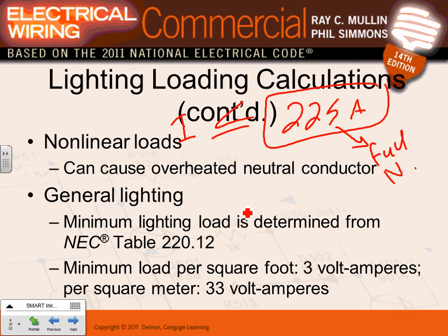So if you can just get up to 225 amp linear load, that would be great. For the load calculation that we want Friday, just get the math part done, and right underneath put full neutral because of harmonics. Did you guys hear me? That's for the receptacle panel and the lighting panel. For the main panel, though, it's going to be more than 500 amp, right? So that's how we do it.